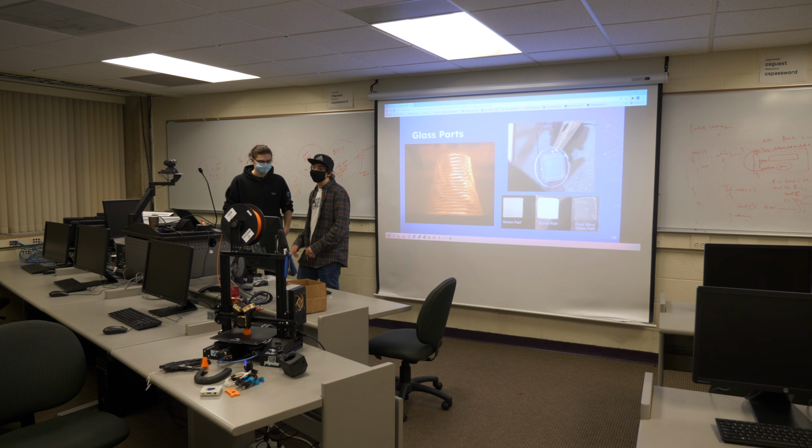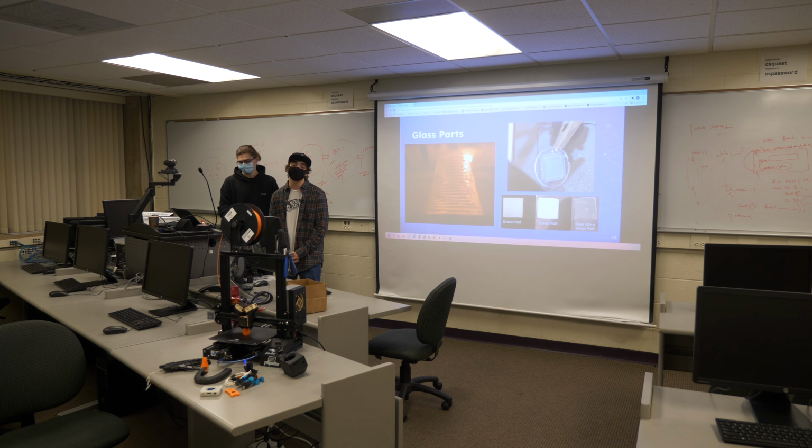Yeah, and you can actually also 3D print with glass. As of right now, there are two competing technologies for glass 3D printing. On the left here, we have an FDM style glass printer, and on the right, we have the process of an SLA style glass 3D printer. The printer on the left essentially just superheats a bunch of glass in a chamber, and that chamber gets pressurized and forced out of the nozzle at high temperature. That was actually developed by MIT.